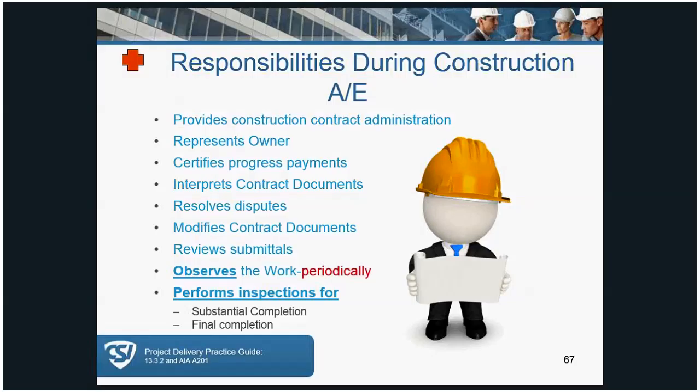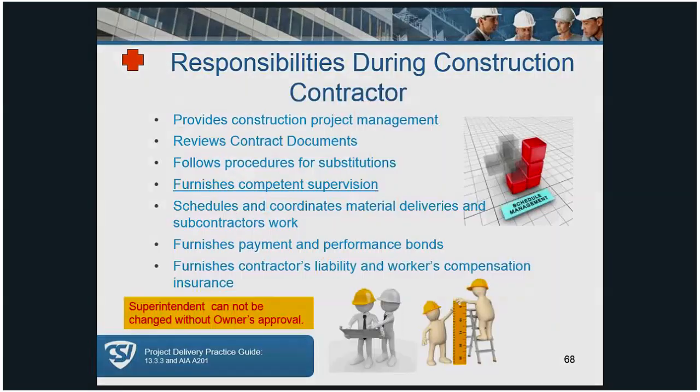The AE, again, observes the work periodically, performs inspections for substantial completion and final completion, interprets the contract documents, and certifies the pay application. But again, you'll see in this list where the AE cannot stop the work. Very important. Next.